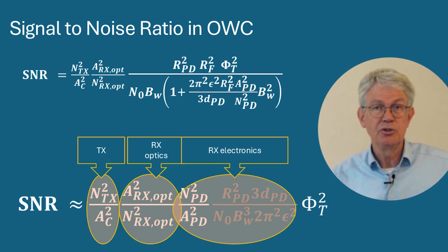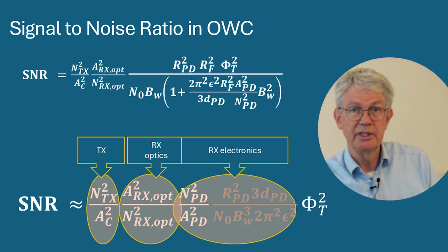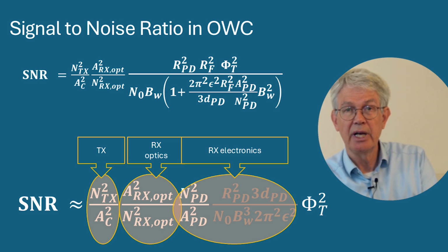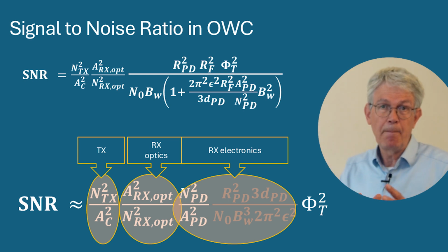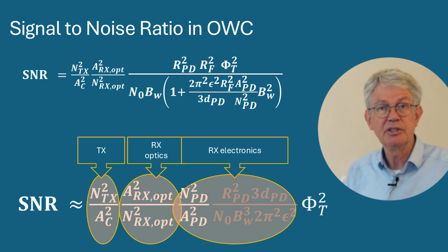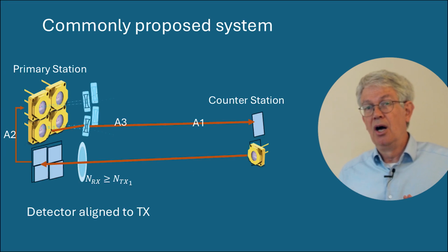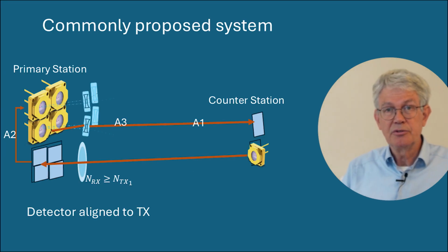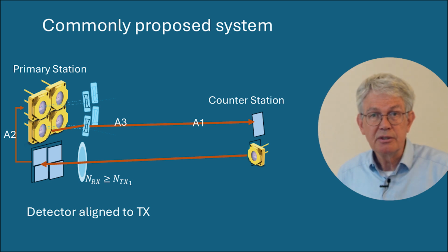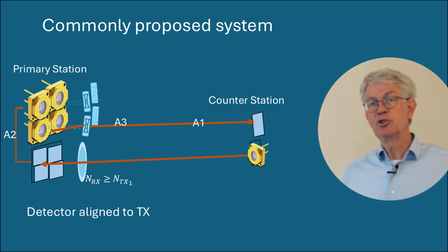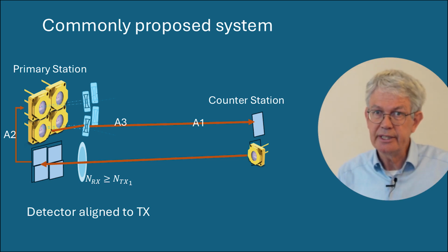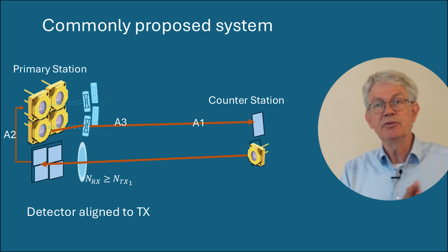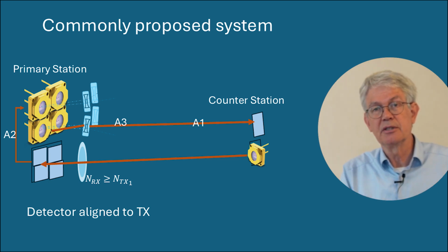So overall, the signal to noise ratio is helped a lot by sectorizing at the transmitter. It's pretty tricky to do the sectorization at the detector. Yes, we like to split the photodiode, but preferably not by using only a part of the optical area, so an imaging system is better. All in all, these trade-offs and design considerations are very different from the transmitter at the receiver. So if we talk about standardization, an important aspect is, can we give designers the freedom to make a different choice for the number of sectors at the transmitter and at the receiver?